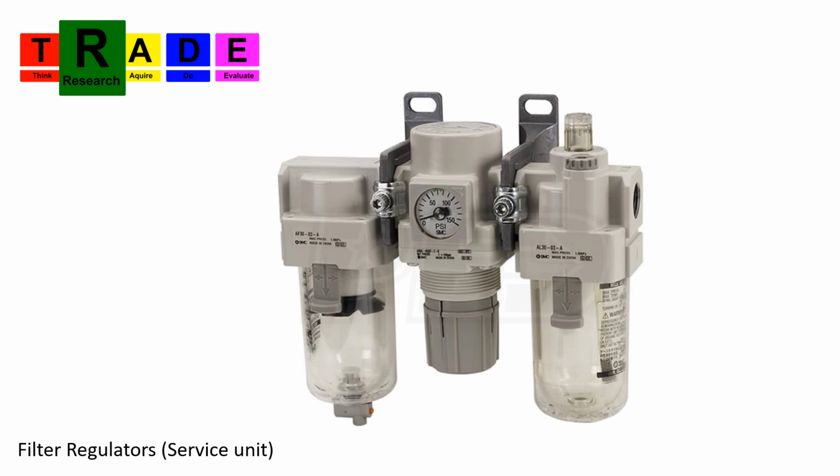A good quality and well-maintained service unit is critical to maintain a reliable system. Make sure you're using the appropriate service unit as well as the correct lubricant. By connecting your pneumatic device to an incorrect air supply, you could be shortening the service life of your component or your system. And you could also void any warranty on your device.